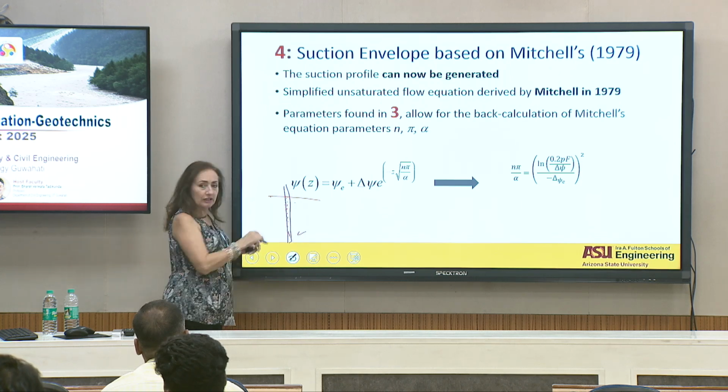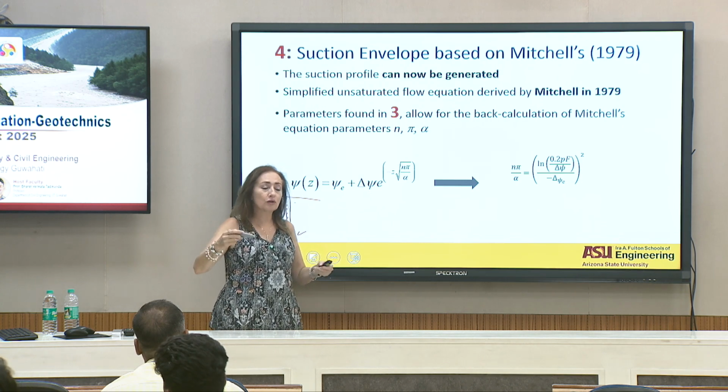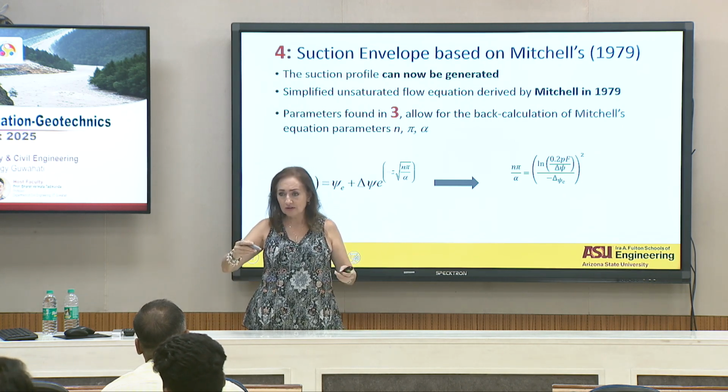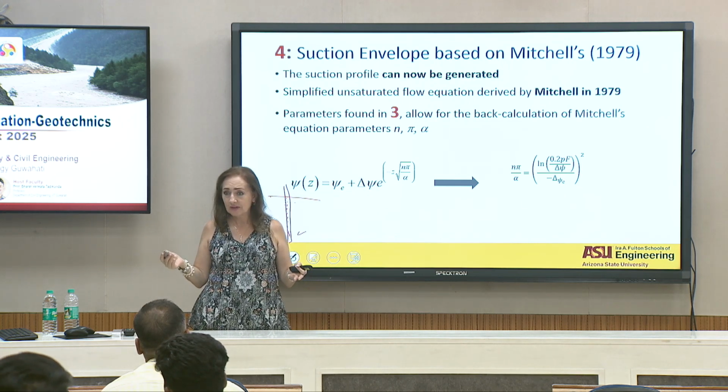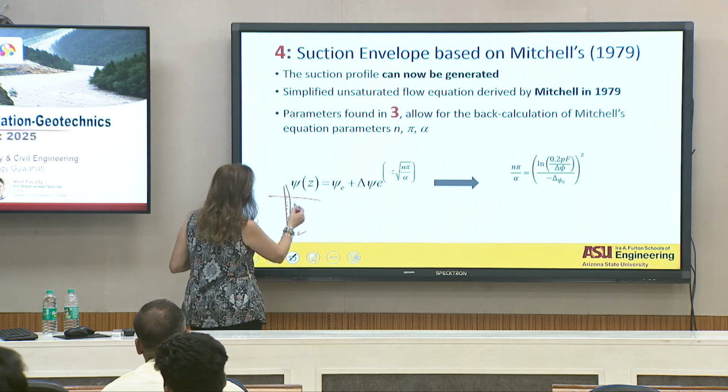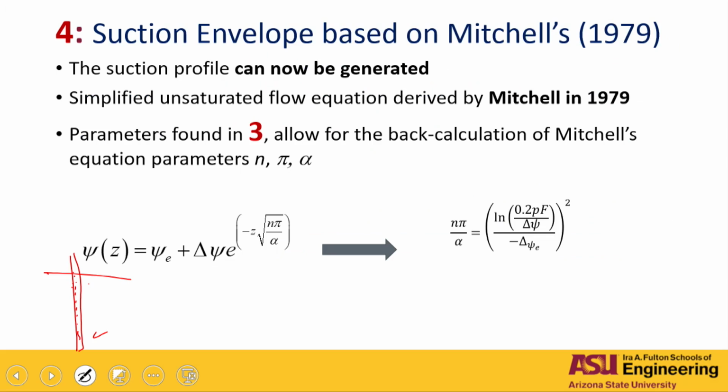They used the same place to go and check again 3 months later, 6 months later, 1 month later, right? And they did this work for about 2 years. They were figuring out how much the water content changes, and you can see the data that they obtained. It was pretty neat. They just did water content determination all the way down, right? They took samples and figured out how much the moisture content will vary at that particular site. And they relate it with the suction.